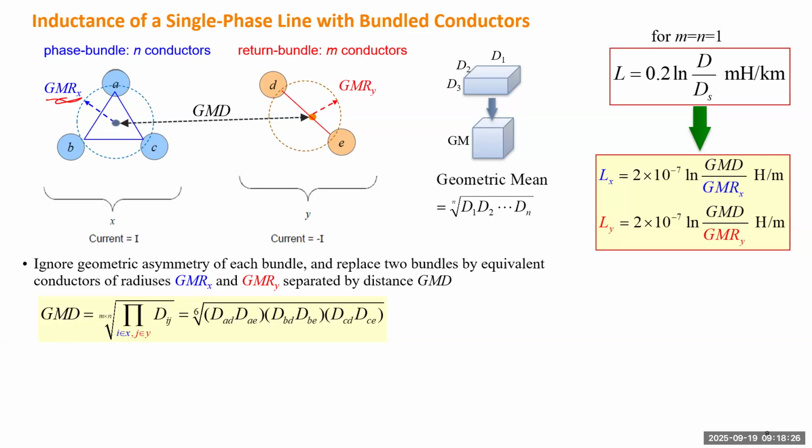We have AB, BC, AC, which are 3 distances between the 3 conductors, but we also need to consider the distance between one conductor and itself. So we need to first define a reference, and for each reference we count all the distances, and by changing the reference we cover all possibilities. So let's select A as a reference.